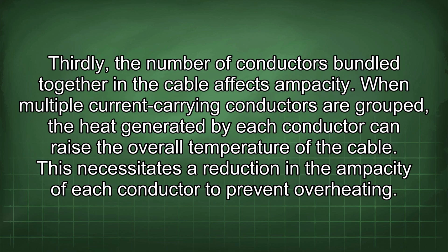Thirdly, the number of conductors bundled together in the cable affects ampacity. When multiple current-carrying conductors are grouped, the heat generated by each conductor can raise the overall temperature of the cable. This necessitates a reduction in the ampacity of each conductor to prevent overheating.